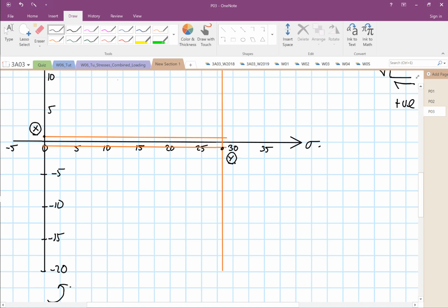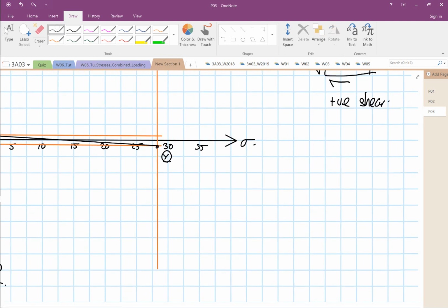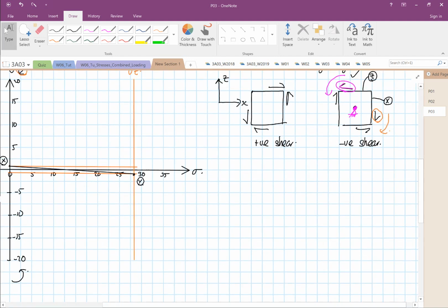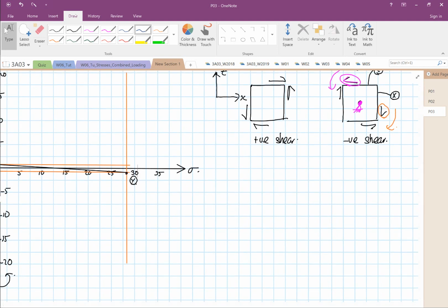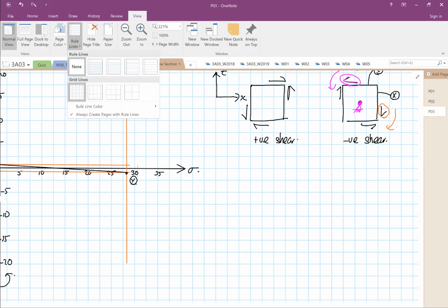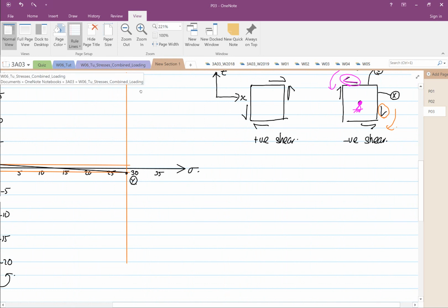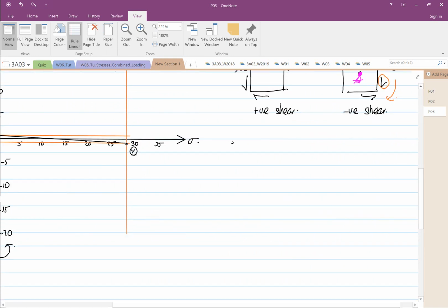For now, if you have a compass, you can immediately draw this. Draw a circle, and then you calculate your normal stress, maximum stress and your principal stress. We can achieve this through calculation also. So let's calculate the center of the circle. No need to memorize any formula.